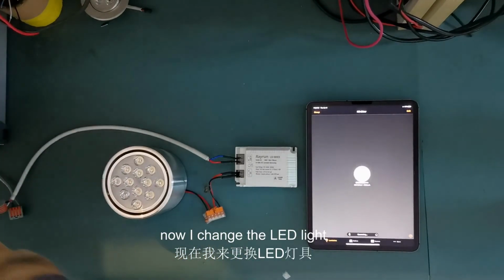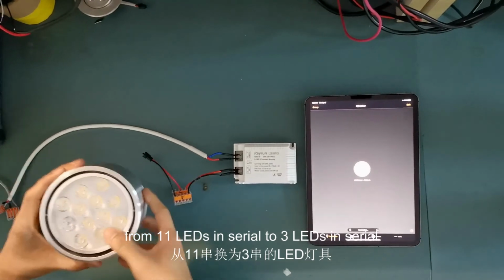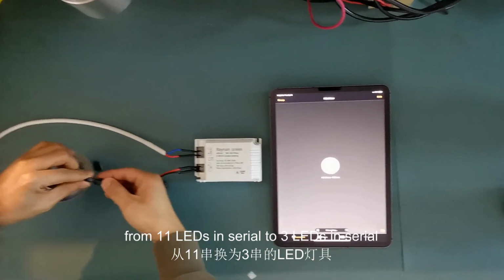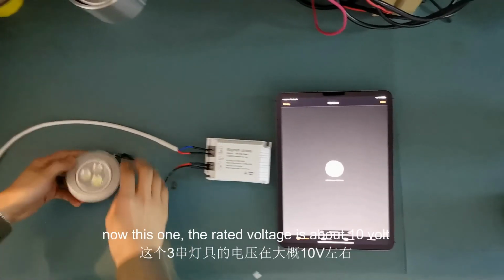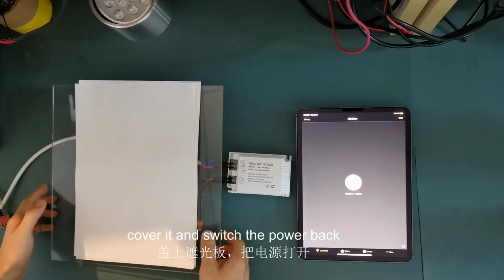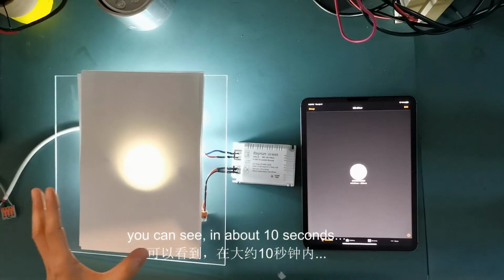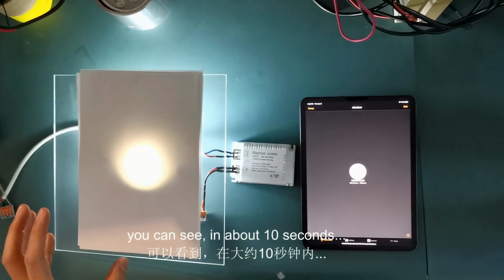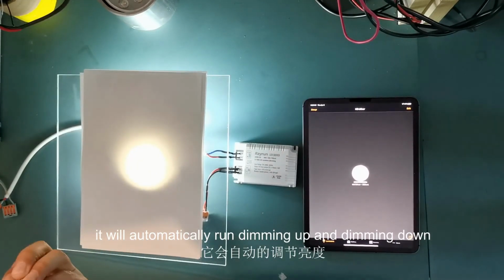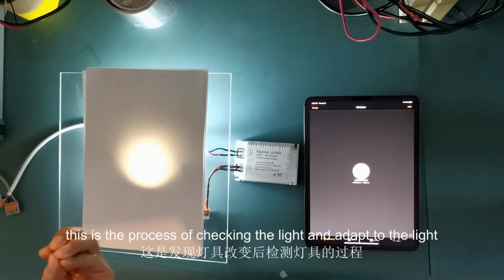Okay, now I changed the LED light from 11 LEDs in serial to 3 LEDs in serial. Now this one's rated voltage is about 10 volt. We can cover it, and then we switch back to the light. You can see in about 10 seconds, it will run automatically dimming up and dimming down.